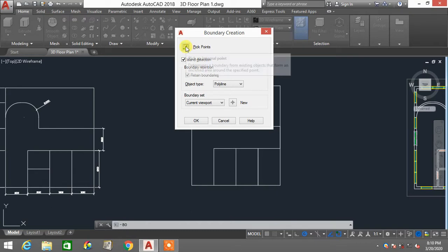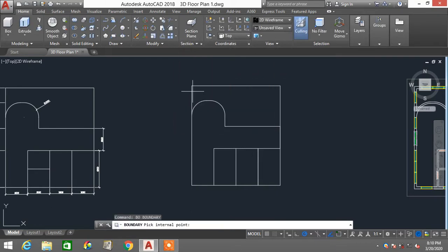So I'll click this particular button and click this area to digital trace that. Click this area to digital trace that, and click all the respective areas for us to digital trace it, and press enter. Now I'll press enter to finalize all the boundary or the digital traces created automatically by the computer.